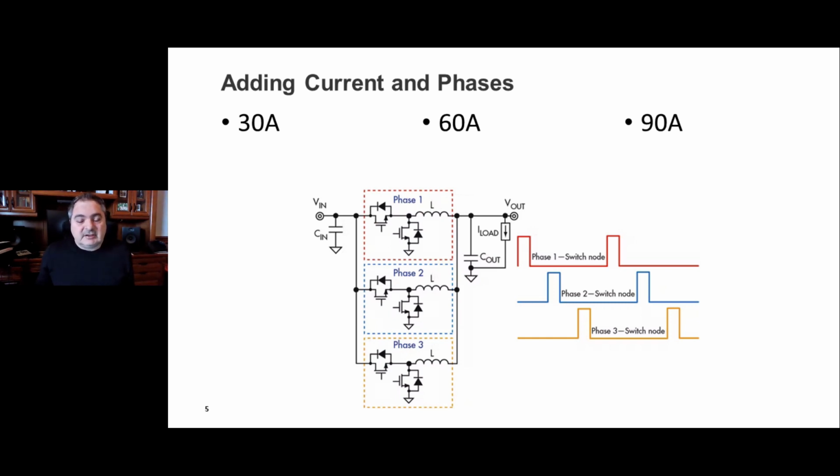So if you've ever tested a power management solution, you can hit it with a pulse, and once in every few hundred or 50 pulses, you'll get a big old glitch. And it's not actually a glitch. It's probably the worst case situation where, because you've hit a pulse, you've done a transient load test on your power management device, but you've caught it at its moment of weakness. Now, those moments of weakness increase as you add phases.